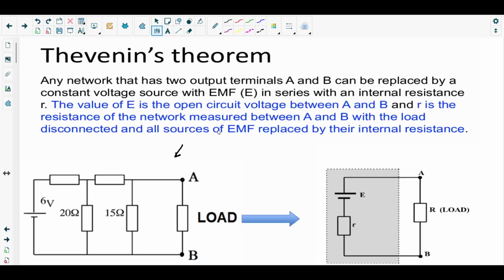So before building the circuit on the breadboard, we calculate the voltage and the current that will be provided to the load. Thevenin's theorem and Norton's theorem are the most effective way to figure out how much voltage will be across that load and how much current our connected load component will get from the circuit. This is the significance of Thevenin's and Norton's theorem.